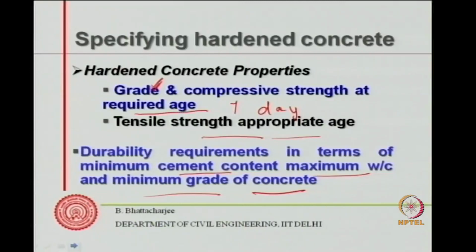So in addition to grade of concrete, I might also specify the strength at some early age. In some other cases, I might specify tensile strength of concrete at, let us say, some age.